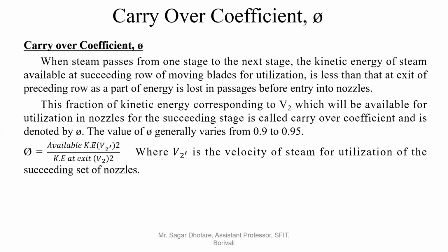Also remember that 100% of the steam never carries over because there is a gap, and in that gap some portion of the steam is lost. So we always consider the carryover coefficient as 90% to 95%: the kinetic energy exhausting from the first stage drops down to 90% to 95%. As the number of sets of nozzles increases, the conversion will be over there.